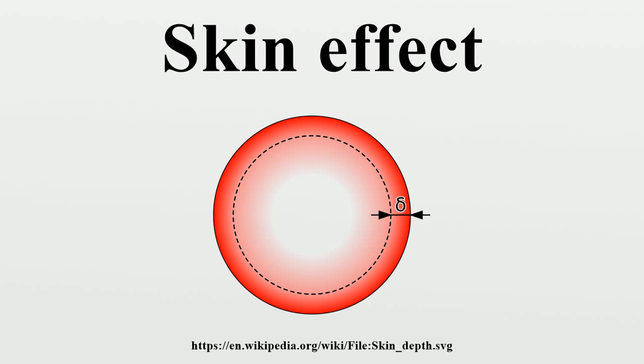Conductive threads composed of carbon nanotubes have been demonstrated as conductors for antennas from medium wave to microwave frequencies. Unlike standard antenna conductors, the nanotubes are much smaller than the skin depth, allowing full utilization of the thread's cross-section, resulting in an extremely light antenna.